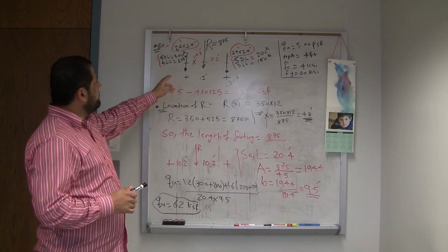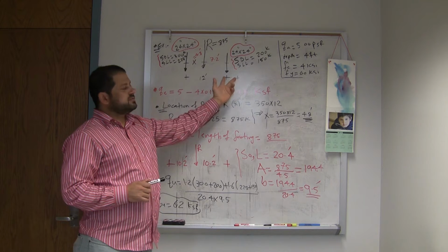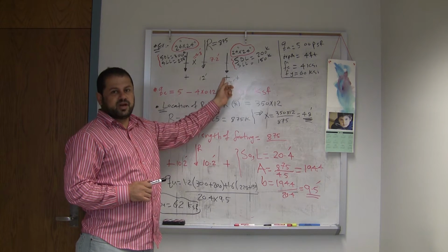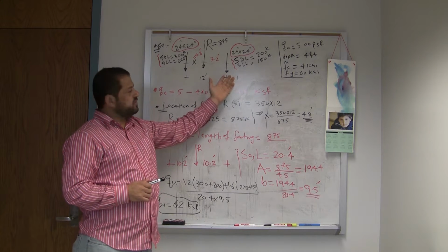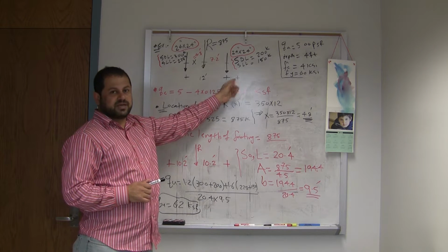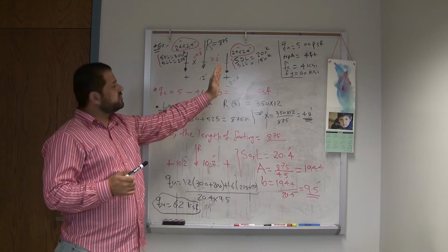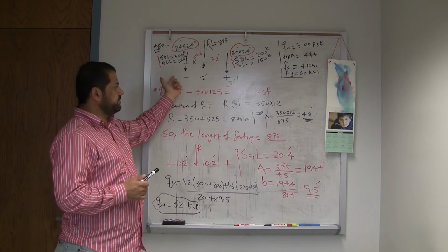So in the example we have two columns, this column and this column, and this is an exterior column. Sometimes when you have an exterior column, you have a limitation on how much you have behind that column. Where is your border line? So the question here is, you have only 3 feet from the center of that column outside. After that, that's not your land. So when you have something like that, usually you try to combine this with a nearby column.